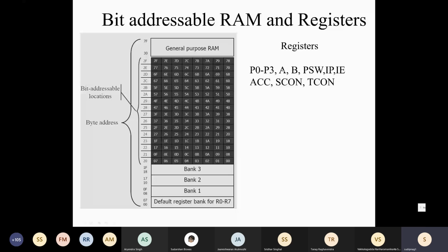You always have to keep this limitation or feature in mind. Obviously, you don't have to remember the exact addresses where R0 to R7 are located and so on, but make sure you consider the locations correctly in your code. These addresses are automatically taken care of by your compiler or assembler, given your syntax and application of the instructions are correct.